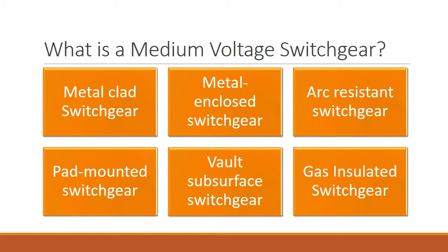Now, the second type that I want to talk about is the metal enclosed switchgear, which is specified in IEEE C37.20.3. Circuit breakers, power fuses, and fusible switches, as well as control and metering equipment, are all contained in metal enclosed switchgear. These devices can be installed in common compartments without the need for separate barriers or compartmentalization that metal-clad switchgear requires. Where the incoming electrical service is usually above 480/600 volts, metal enclosed switchgear is used in commercial as well as many industrial installations.